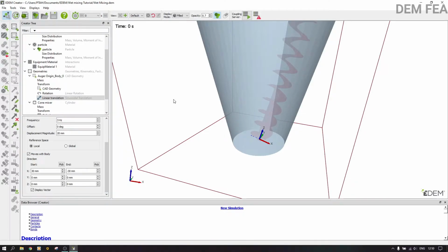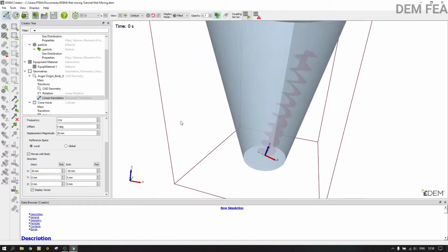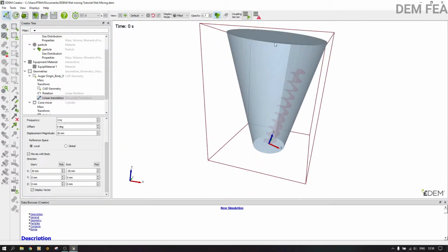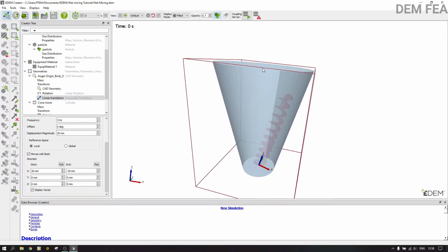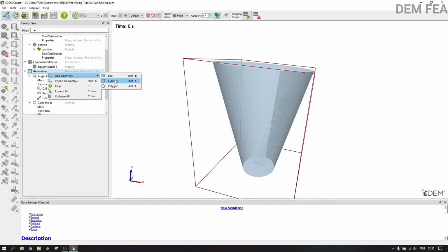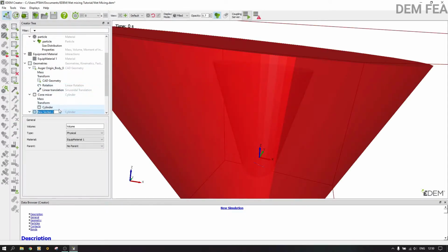Now the next thing that you want to do is to add the tubes. Now for the tube, that's where the spray will be falling from. We need to put it here at the top, almost at the top. Now we need to create another geometry. So we add geometry, a cylindrical. This now will be my factory. Now I call it spray factory, or the tube, because it looks like a tube.